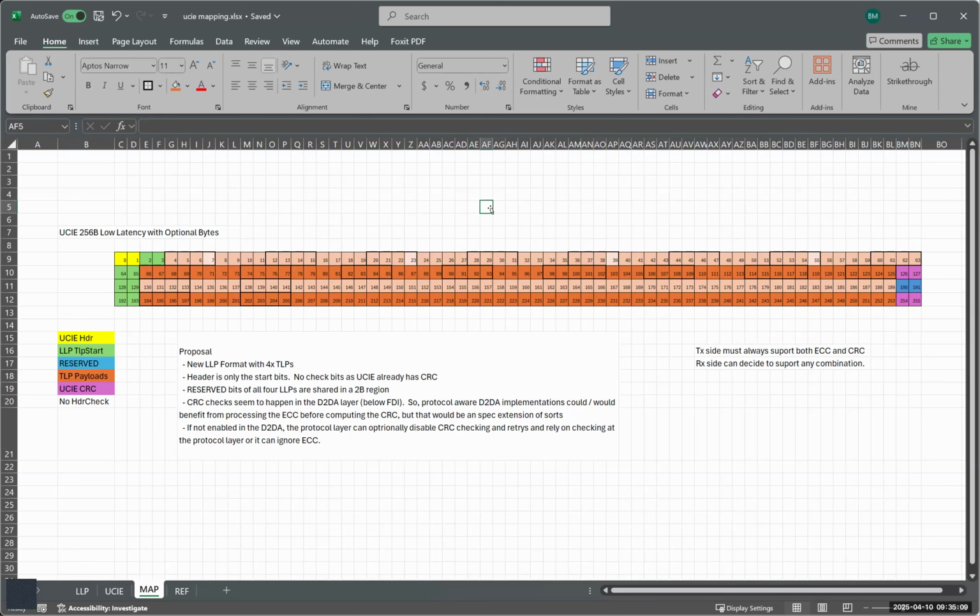You have to deal with unaligned granules, because the granule alignment is different from the first fragment. I don't know if UCIe has a name for the 64-byte chunk, but if you want to call these rows fragments, in the parlance of the transaction layer spec, the first fragment aligns its granules based on the first byte.